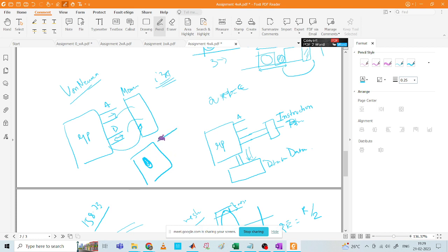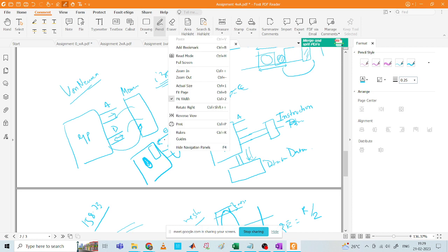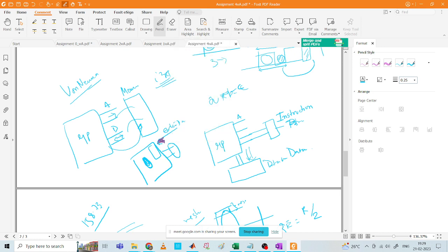At the same time, some external data is coming. So the microcontroller gives up the control of the memory, and the controller takes control of the data bus and puts the data directly into the memory, without the intervention of the processor.